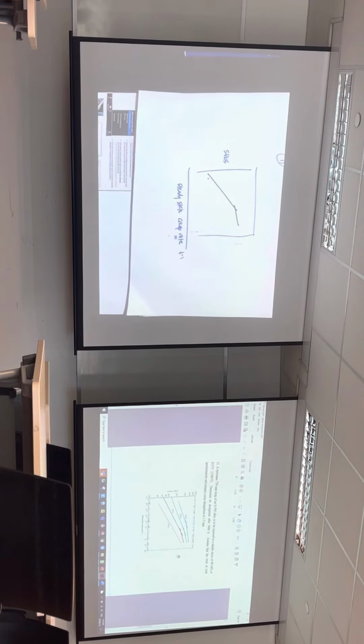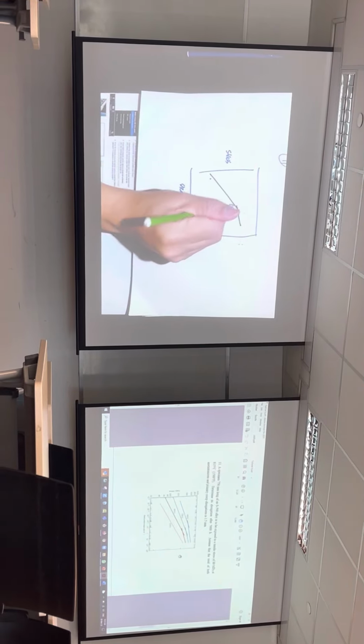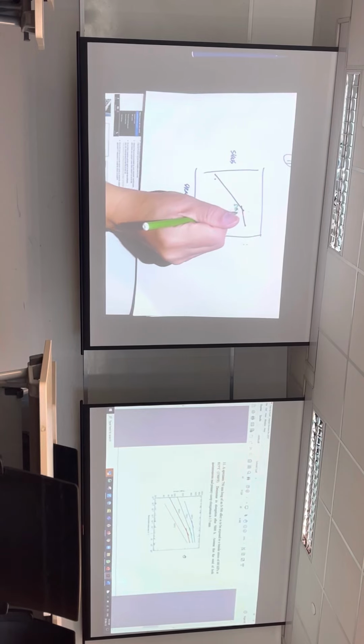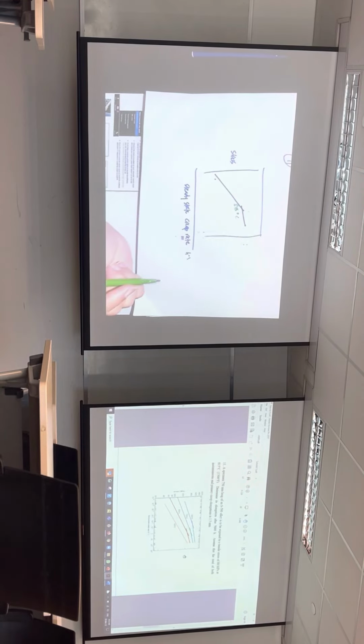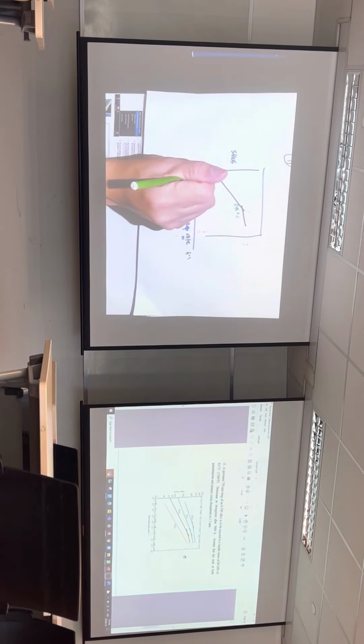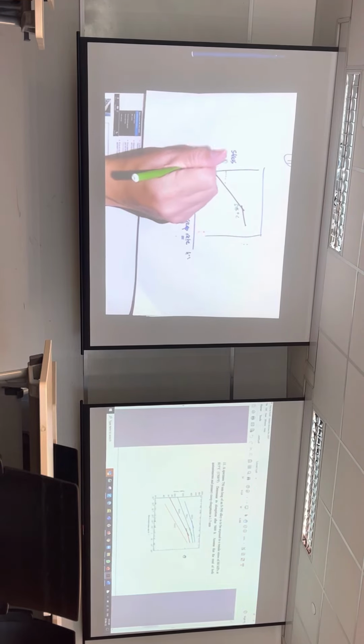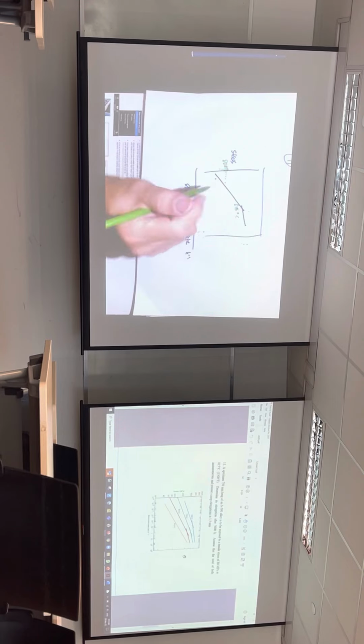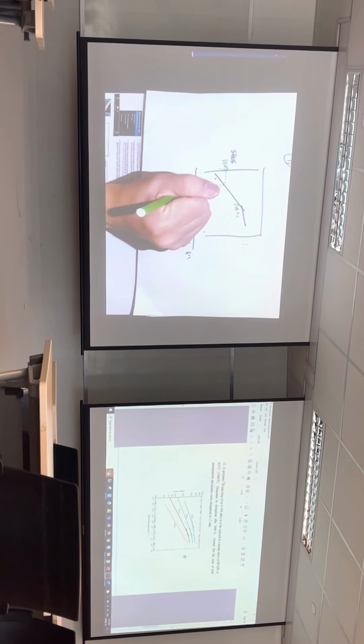If this is 815, it says exposed to a tensile stress of 80. So if you go at 80 megapascal, you'll be able to figure out the creep rate.